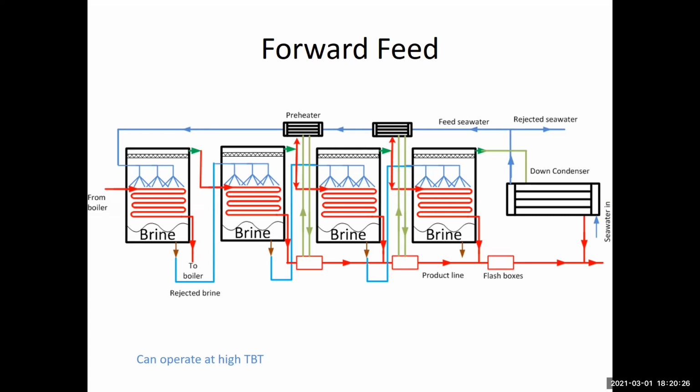What about the couple of black boxes that we have on the top here? These are a couple of heat exchangers. And the reason for using heat exchangers here is we'd like to preheat the feed. The feed has increased from T cooling water to TF, but we need to increase its temperature from TF to TF1 or TF2 or whatever.